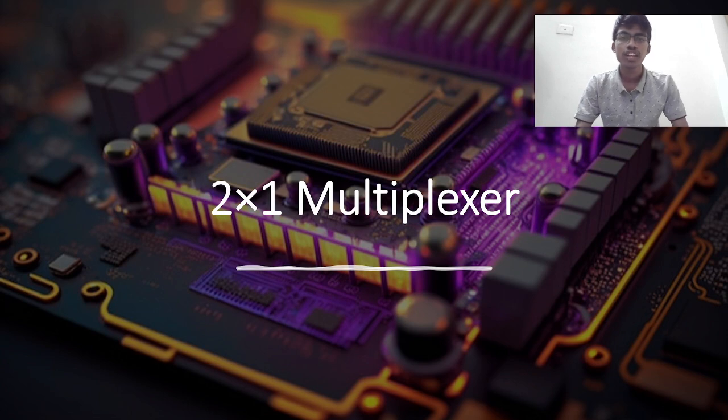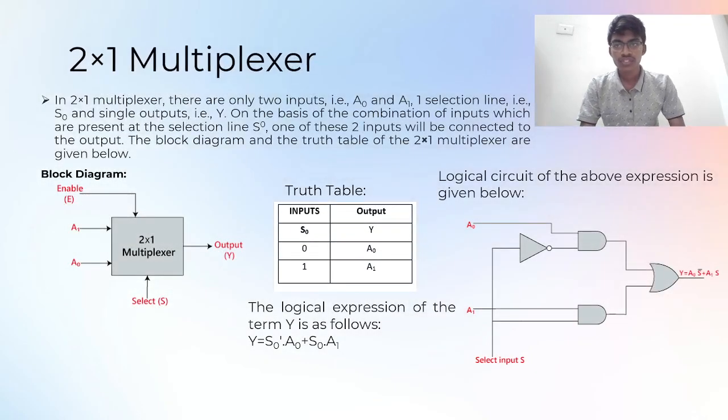Now let us look deeply at what is a 2 cross 1 multiplexer. In a 2 cross 1 multiplexer, there are only two inputs. So 2 represents the number of inputs, cross 1, where 1 represents the output which is produced, that is a single output. It means only one selection line is used, that is S0. The single output is determined based on this selection line. On the basis of the combination of inputs which are present on the selection line S0, one of these two inputs will be connected to the output.